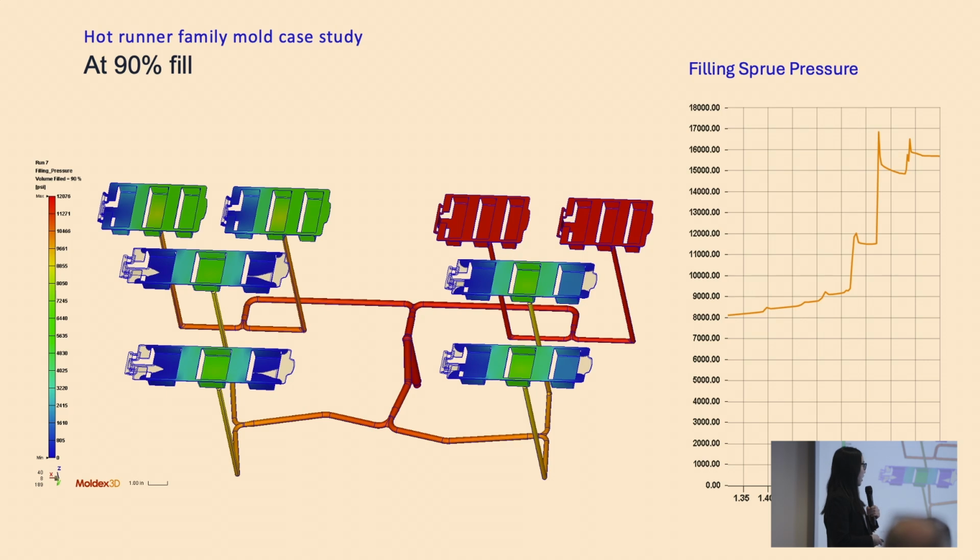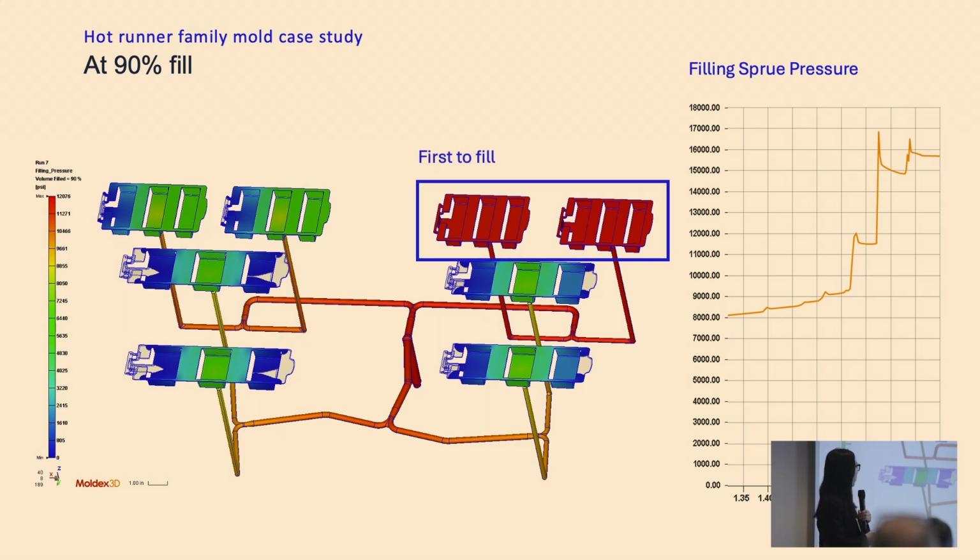So with this case study, they ran a simulation with our software, and you can see that at the 90% filling stage, the first, smallest parts are filled first, and from the filling sprue pressure, you can also observe a pressure jump when the first parts are filled.